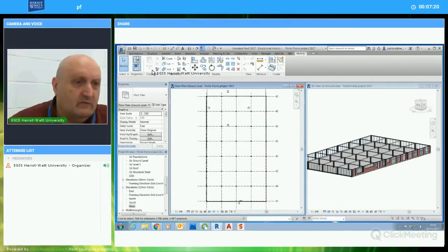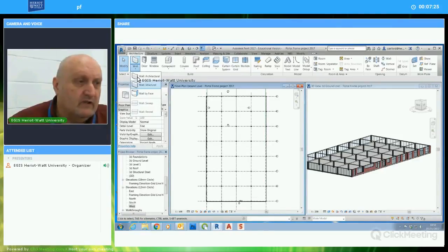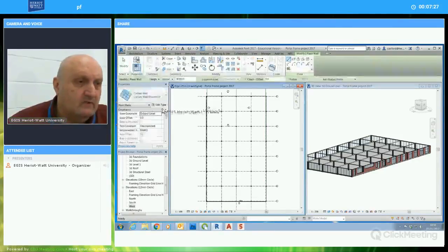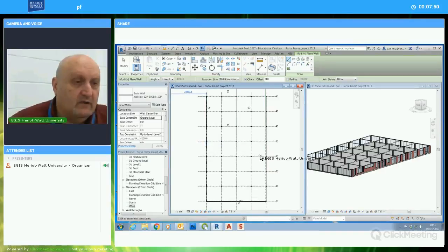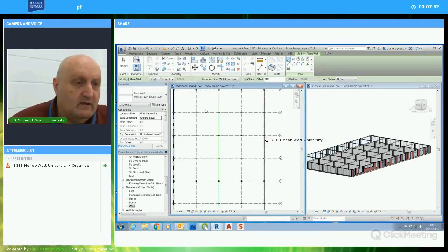You'll see what I mean when I do it. The first thing I've got to do is choose an appropriate wall, and I'm just going to use an ordinary block wall, an ordinary partition wall, but with block rather than studs. So that one there, it's finished in plasterboard on either side. I'm just going to leave it like that as well. I'm happy with this wall interior. It's got 12mm plasterboard both on the outside and the inside, essentially a block wall. So I'm going to select that wall type, and I want to come in here,